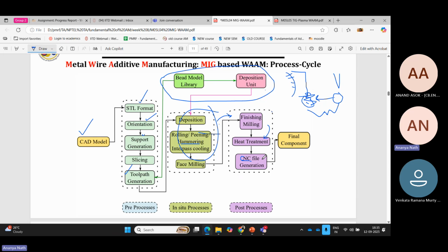Or if it's not a computer integrated machine, then that machine should understand what you're putting. Just for example, if you are using a drilling process, then you can set the drill bit rotation speed. You can set if it's going to be clockwise or anti-clockwise, and then you start the manual drilling. You pull the lever and slowly you come down to the material.